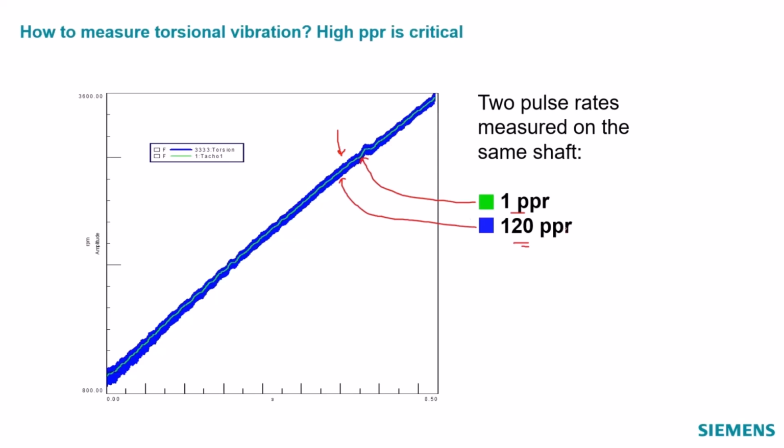Yeah. When you're driving around in your car, Charles, what type of encoder do they have for your engine RPM? You have like one of those fancy cars that shows the engine RPM? I guess so. I wouldn't call it fancy. I would say 1 pulse per rev. Yeah, they purposely don't let you know that your engine speed is varying up and down, right? People would kind of maybe freak out if they saw it jittering constantly. There can be an advantage to showing just the overall RPM and not showing those fluctuations.